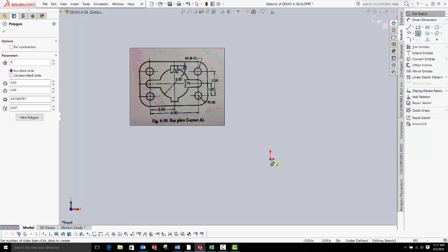So I'm in a sketch currently, you can tell by looking at these, and so I'm just going to pull this out, and over here is where we control the number of sides. And it's great fun to run this up to 50 and watch it make a 50-sided polygon. Realistically, you keep it between 10 and less, 8 or less most times we draw with it. And we'll go all the way down into a 3-sided object or 4, but when we start getting into 5 and 6, that's where it's most beneficial for us.